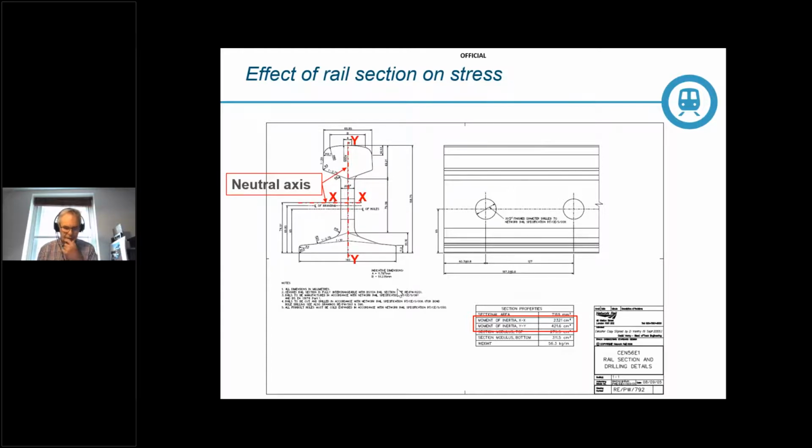In reality, the loading and hence the stress distribution is complex, as the rail is loaded both vertically and laterally, which leads to torsion in the section of the rail as well. And it will be subject to residual stresses, typically from roller straightening of the finished rail, and these will have an impact on the fatigue and fracture toughness. And remember that thermal forces are distributed uniformly across the cross-section, and for most of the year, rails are in tension, as the rail temperature will be below the stress-free temperature. And again, this will cause cracks to grow, but is obviously the key to resisting track buckling.